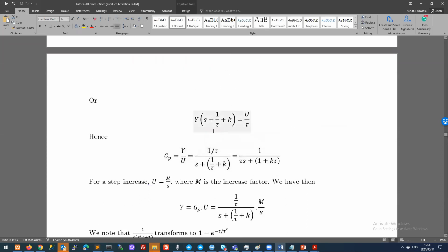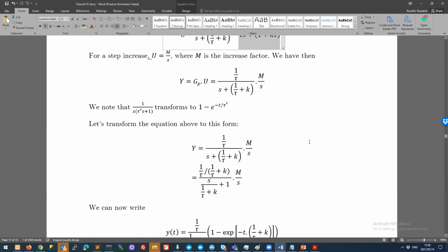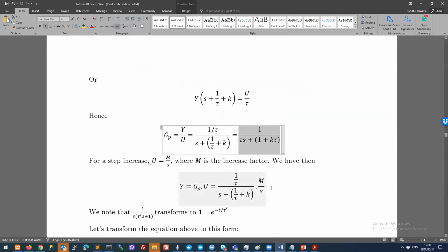Besides Laplace transformation, now that you have extracted the transfer function itself, you can very easily think about, if I apply a certain control strategy using a step function, or using something else, how is my system going to respond? So that's the beauty of transfer functions. They make it very easy for us to consider the impact of a control strategy on an output variable. Okay, so that's what I wanted to cover today. Any questions or comments there?